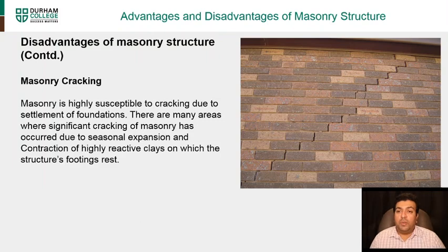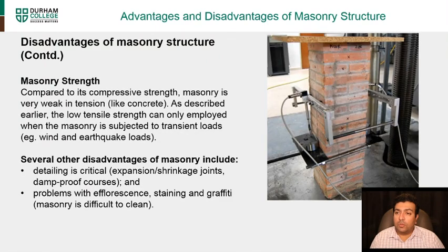Another disadvantage of masonry is that it's not one cohesive structure. If the mortar is not prepared properly, or is not placed properly in the gaps, it is prone to cracking. These cracks can be fixed with grouting, but this is one of the disadvantages of masonry structure.